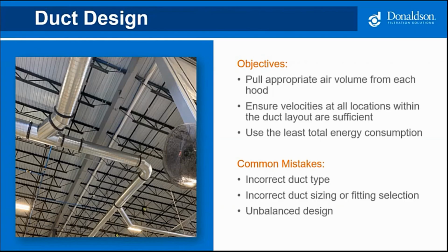Now, common mistakes in ductwork. Number one, the incorrect duct type, which we'll talk about. Secondly is incorrect duct sizing. That I see more than not in most applications. And then number three, getting an unbalanced design in a system, which we're going to talk about.